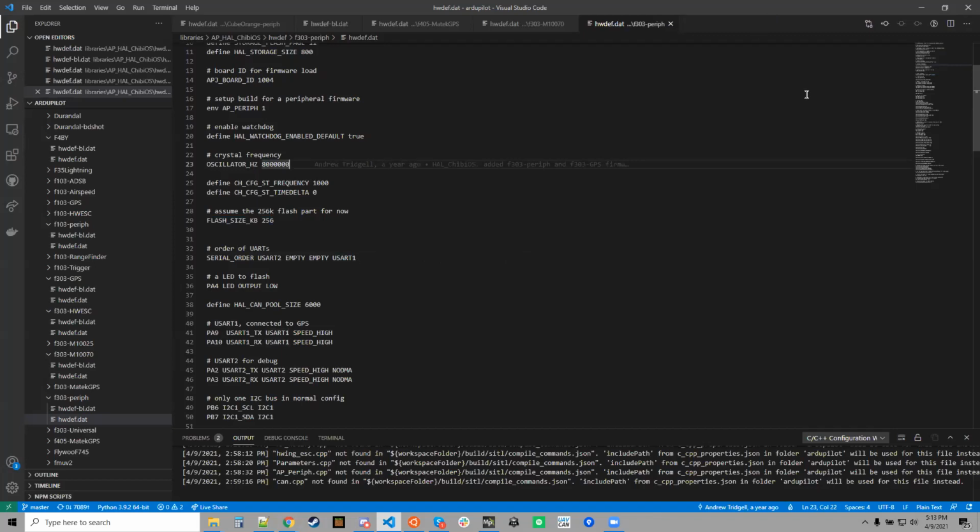The one thing that I've worked with quite a few vendors bringing out new AP-perif devices. And one of the things that often causes problems is getting the crystals right. So we've now added support for putting 0 as the oscillator frequency. And what that means is it uses the internal oscillator on the STM32 instead of using the crystal. And that's particularly good for debugging. If you've got a crystal problem, you can turn off the crystal and just use the internal oscillator. So you don't need a crystal at all. You don't need to attach one and get it working like that, and then get it working with the crystal, because it's surprisingly common how often there are mistakes in prototype boards with crystals from multiple vendors. It's one of the more difficult things to get right.